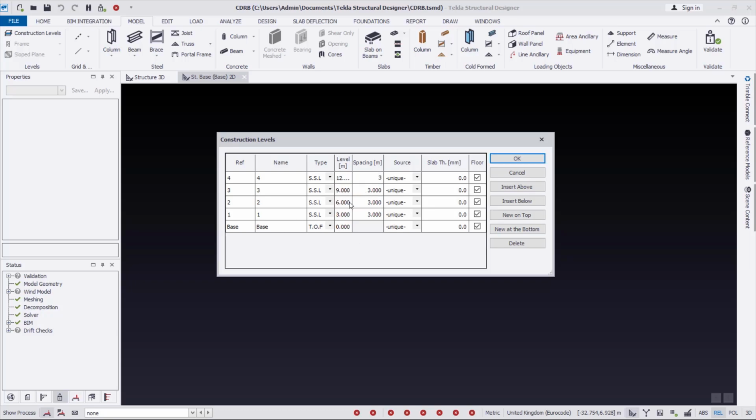And again over here, where you have the source, is how to make stories similar. For instance, if I want to make story 1 similar to story 2 and similar to story 3, I change these provisions to 1, because here we have it to be story 1. This simply means story 1 and 2 are similar. I want to make 3 similar as well, so I change it to 1. So all of these are similar. The only unique story we have is this story 4 right here.